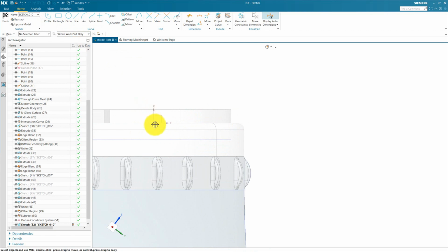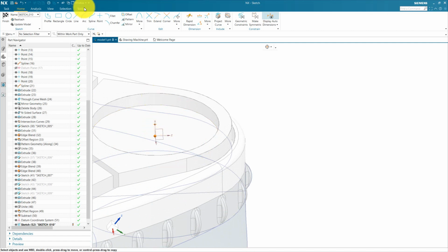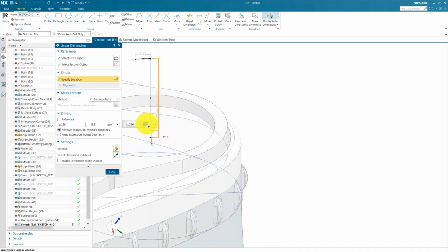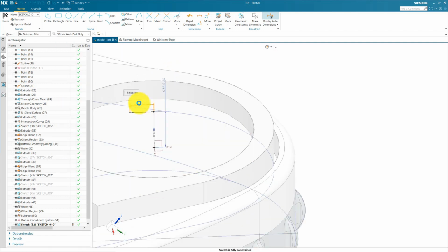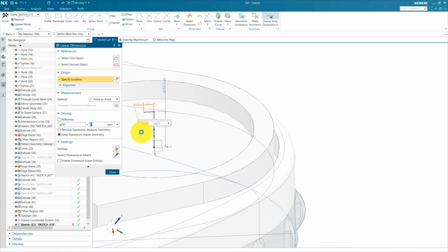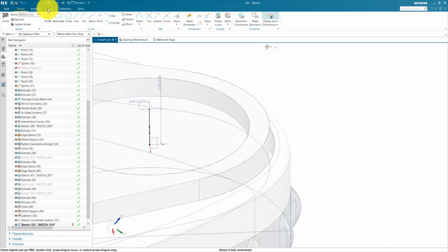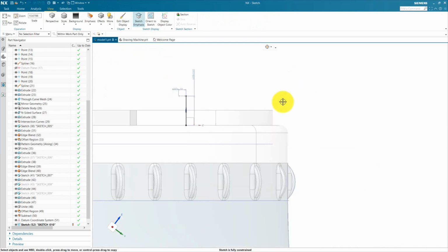Now we create a section. For example, this is the bottom of the circle. Okay, line, use profile, and the length, and then this line we use for reference to apply the tangency. For example, this length is 3.9, okay, and that is 1 mm. It's only for reference, so convert it to reference and orient the sketch.